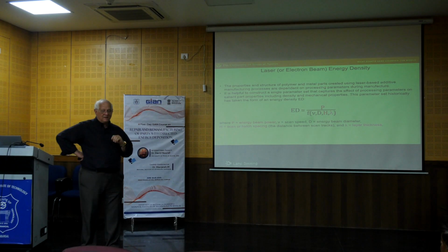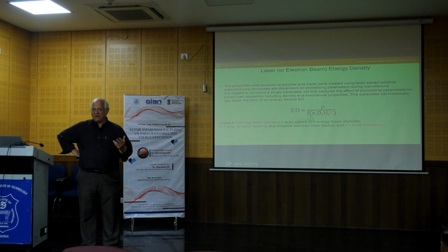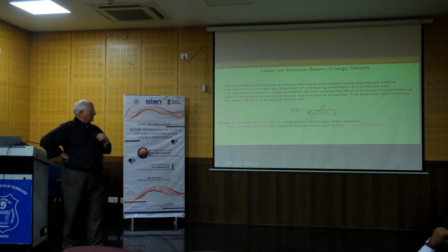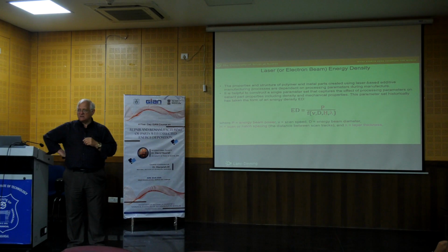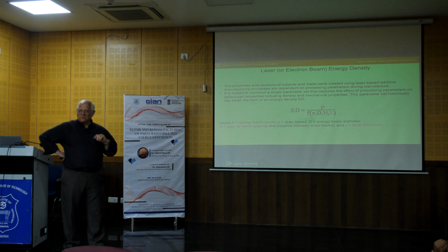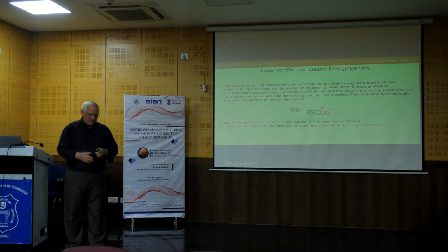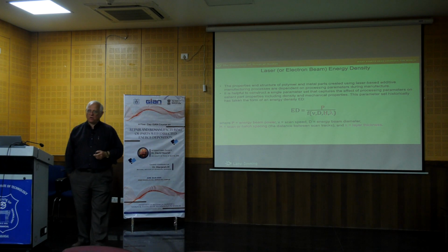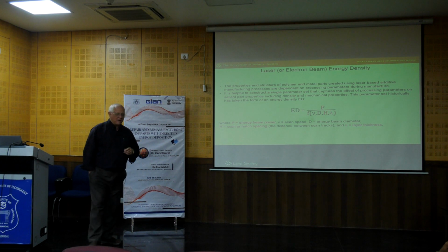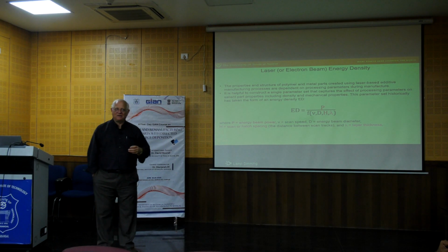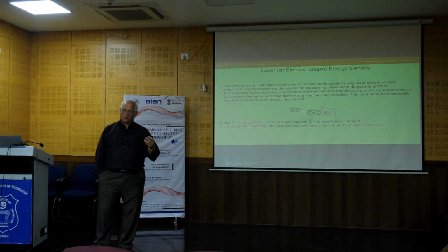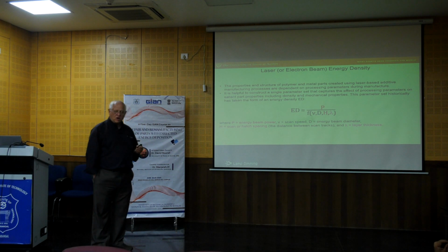Historically with additive manufacturing of metals, again DED and powder bed, for the fusion processes, we have a thing called an energy density, and it's always equal to the power of the energy beam divided by some function of the other parameters. What that function is depends on your assumptions, and so there are a variety of forms for energy density, and I want to go through and talk about those.